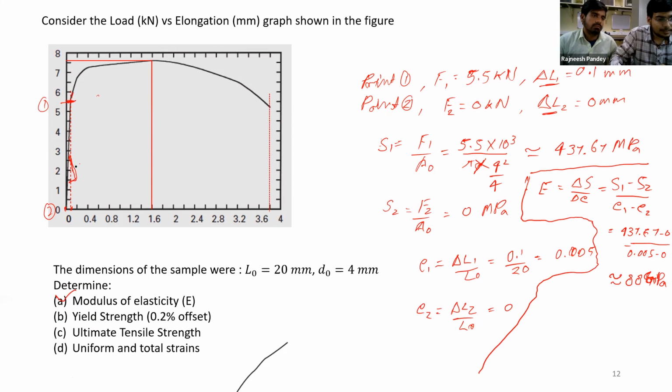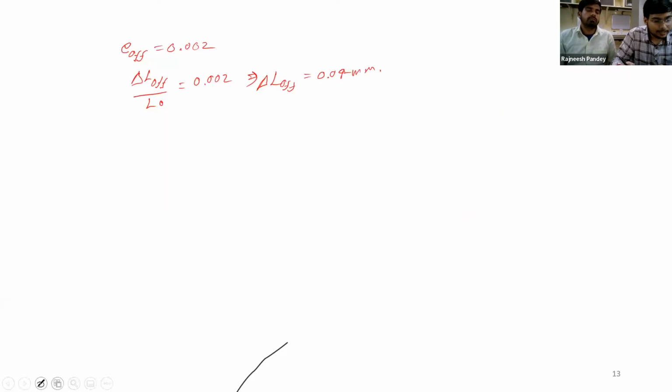Let us keep this as this green one. So it would be around this 0.04 to here. It would go approximately. This is causing a little bit of a problem. So basically, it will intersect at this 6 kilonewton load approximately here. So what do we get from here? We get the value of force at the offset line, which is nothing but 6 kilonewton.